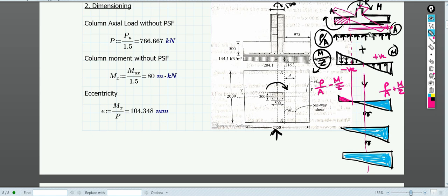Okay, so that is why it is not suggested to have tension. So always try to have a compression. That means this is the minimum criteria to design a footing. So the stress distribution should be something like this, where on one side we can have a minimum of 0 and on the other side we can have the maximum. That means tension should not be there, tension should be 0.